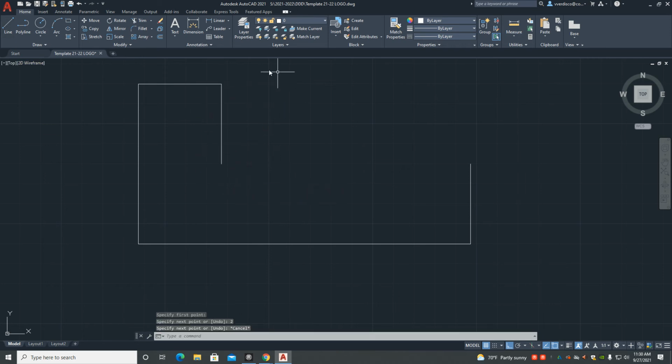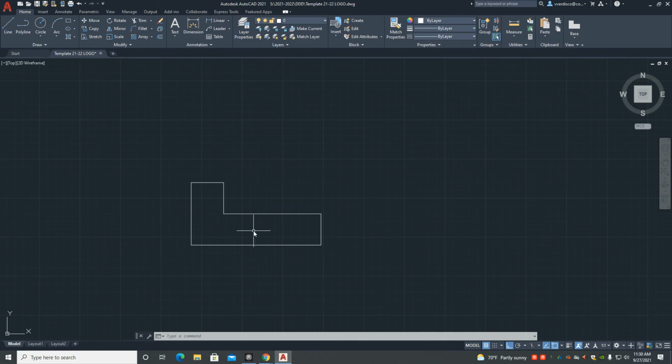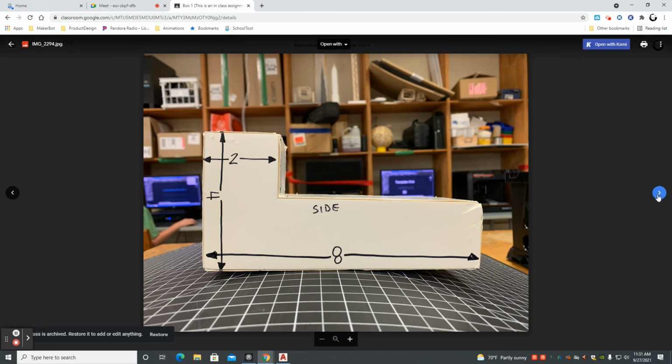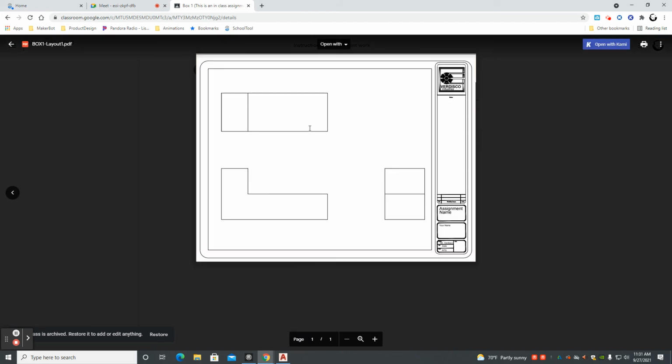That 3-inch measurement is not on this view. But we have now a line here and a line here, which we can connect. And that is going to give us the line. Notice it was 6 because this is 8 and we figured this was 2. 8 minus 2 is 6. So there's the first view. We're all set. Let's go ahead and now create this top view.